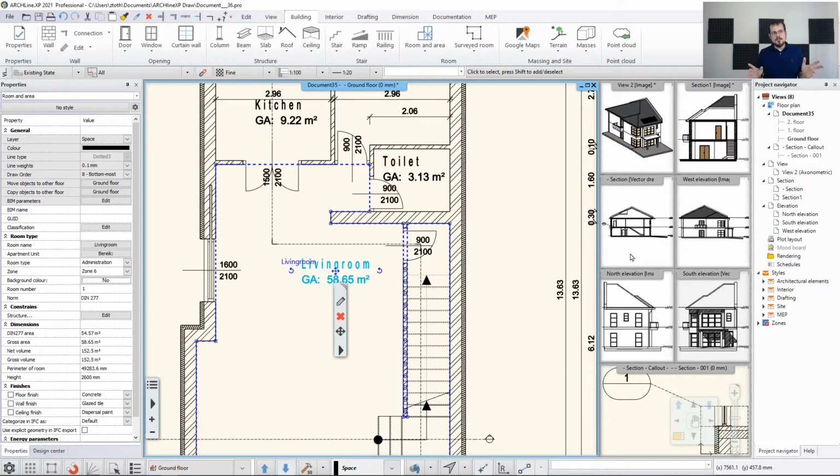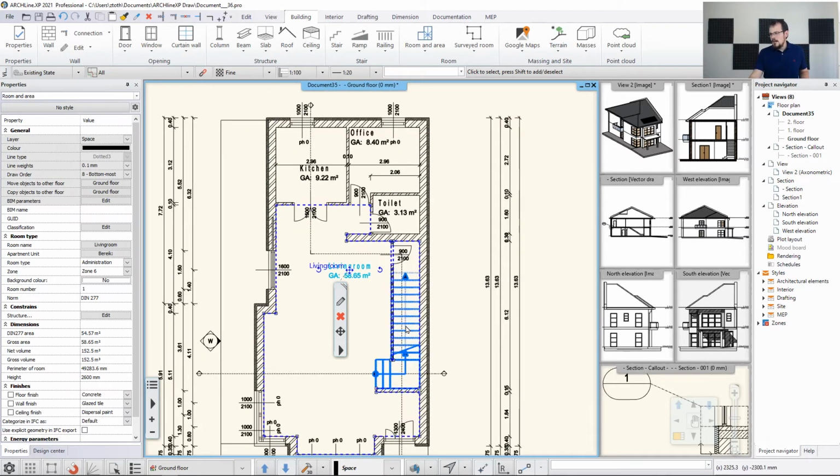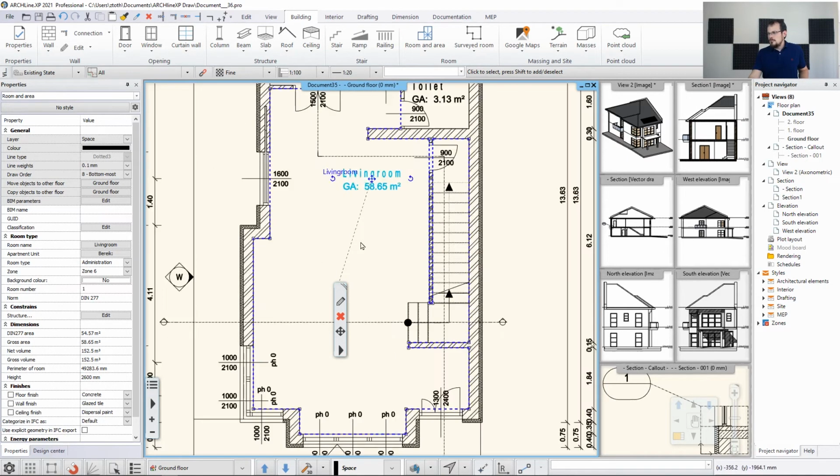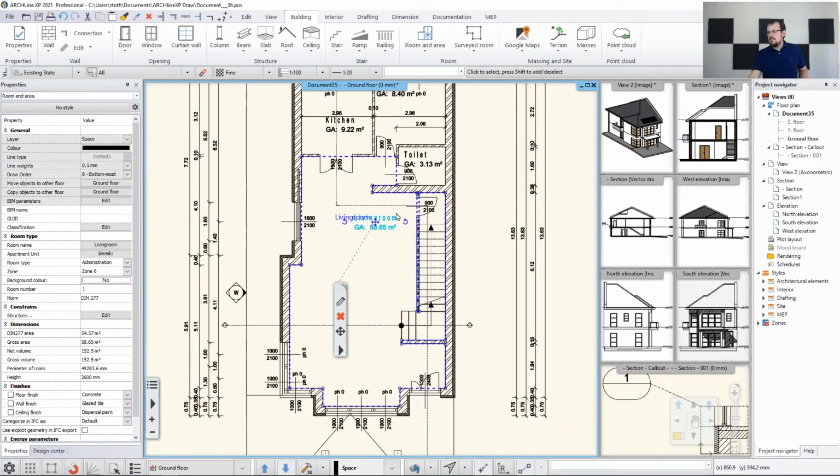Now, this is one way to do things, but as it happens, we have to be a bit more tricky this time, because we want to break this single room, which is almost 60 square meters, into two separate locations. Now, the software is not able to do that by itself because it would recognize the contours. So what's the method for manually designating room shapes? This would come in handy when you have a situation like this one, a room with a double purpose, or maybe you have an external seating area, like a barbecue pit or something like that. You need to be able to manually track the contour of these elements.